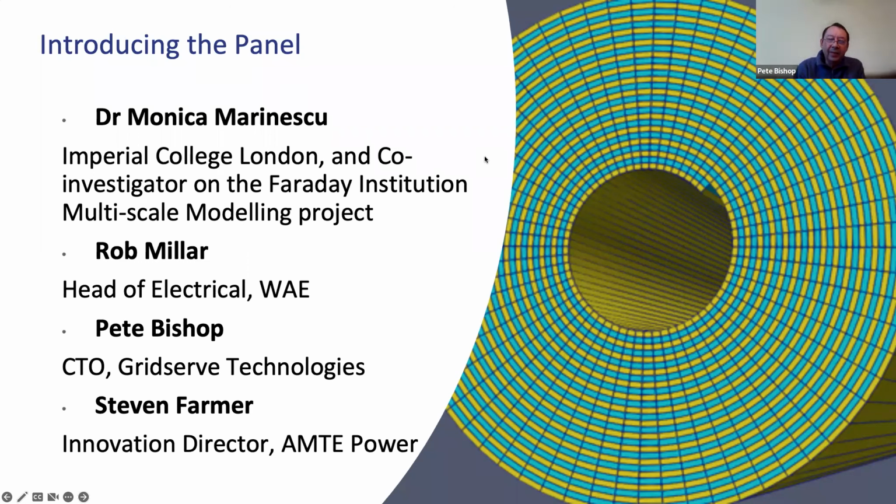Thanks, Peter. It's largely around the two areas you've already mentioned, actually. One of the biggest areas we see the challenges in is in the thermal system design, particularly in achieving uniformity of thermal conditions across all the cells in the pack. So the ability to have cell parameterization that supports full 3D modeling at pack level, and this is particularly challenging when we're doing cell to chassis, which we are with some of the more innovative niche vehicle manufacturers, because we have to take into account the full 3D CAD model of the chassis and the pack design as well, and all the thermal paths through that. So it becomes quite a monster in terms of simulation.